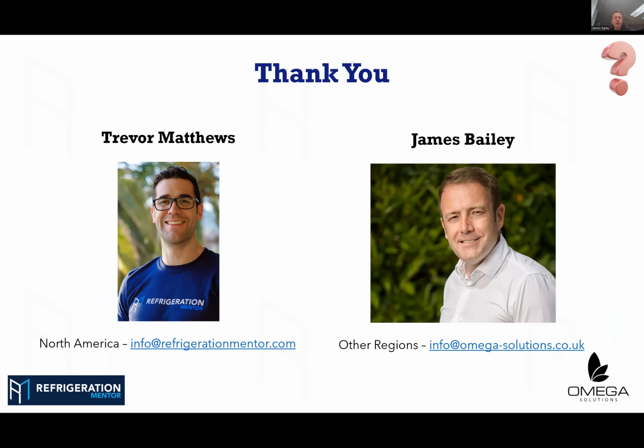Without doubt, Trevor. What we need to, the penalty that's really important is the penalty that you add as the design entry. So on a suction group, for argument's sake, if I set my penalty to 2 Kelvin, that's what the system's going to work within. If you put 3 Kelvin, it's going to work within that. If you put 1 Kelvin in, it's going to work in that. And you're absolutely right, Trevor. The implication of that on a larger system, it might take your largest suction pipe work going back to your rack header from 2 5/8 to 3 1/8. That's going to cost more money.